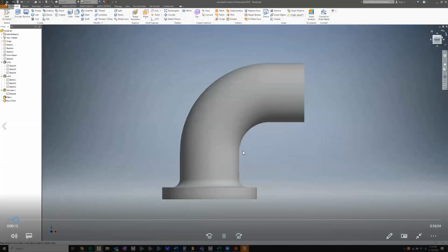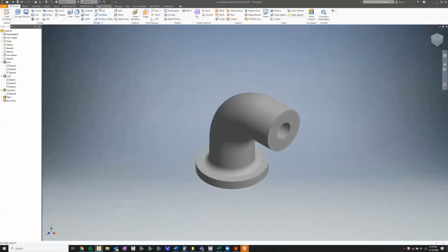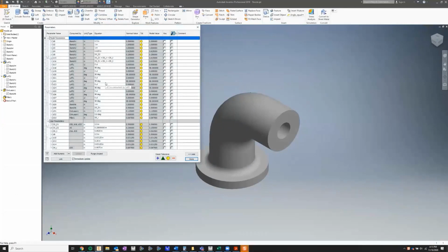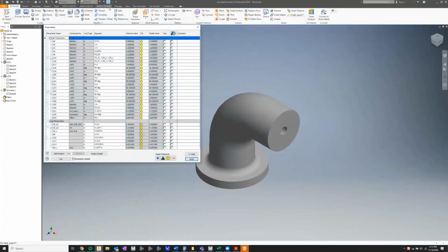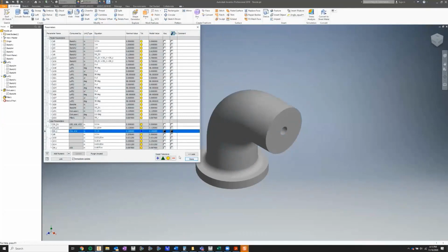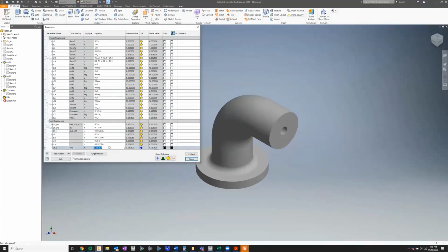So what you see on the screen here is the geometry part. Now this is in Inventor, and the idea of setting up the geometric parameters in your CAD tool is very well highlighted. You can see John setting up those outlet diameter parameters within Inventor. You could do these same steps in whatever CAD tool you're using right now. I, for example, do not have Inventor, so I would do this step in SpaceClaim.